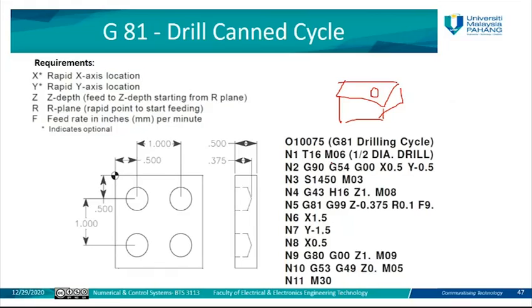So this is one of the examples here of G code to create a hole. As you can see here, this is the point where we give the order to create the hole, which is G81. Then we use G90 here for clearance, as we mentioned before. Then this is the depth of the hole, and here is the R plane. Then what is the feed rate? After that, it will create the first hole, the second hole, the third hole, and the fourth.